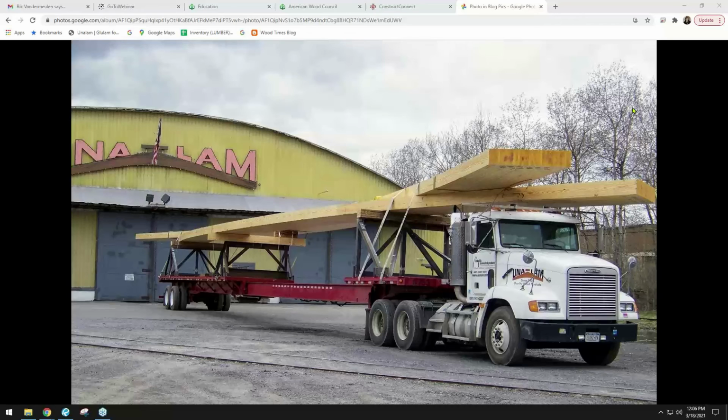Yeah, I think that would be its own design thing. I don't know who would. There are requirements for pressing the adhesives. We saw Liz shared some pictures of that. I would not recommend field construction of glulams because again, you'd have to have them inspected and have a stamp applied. So anything that doesn't have a stamp would not necessarily be considered code acceptable material.